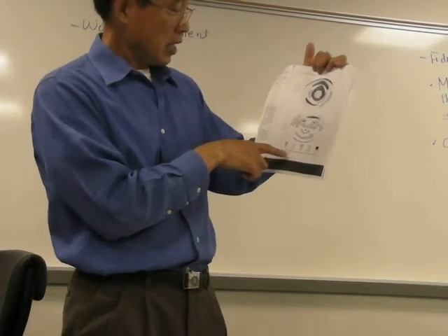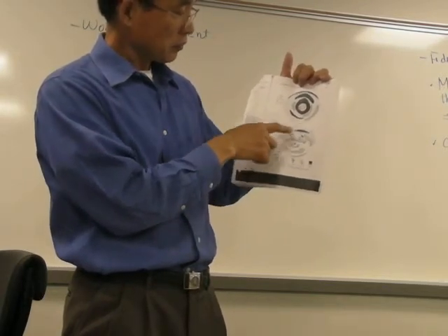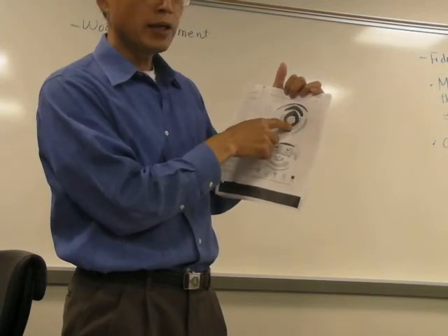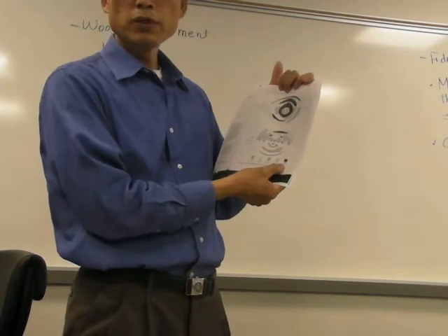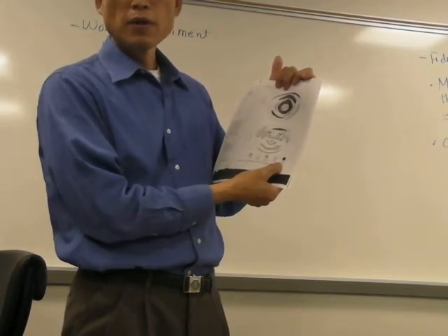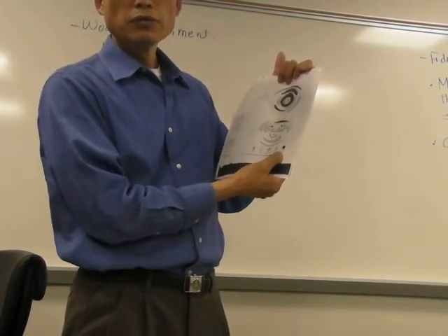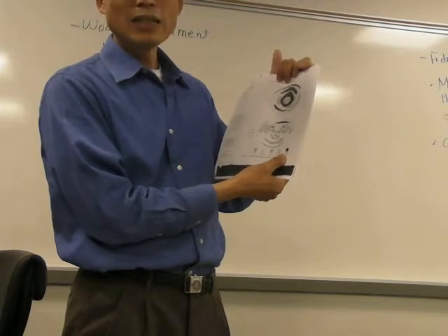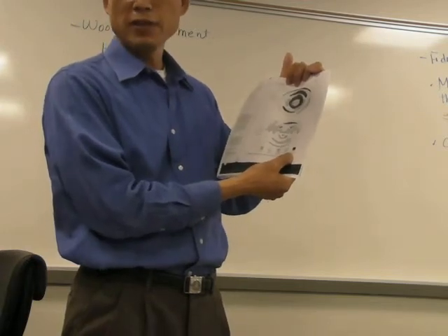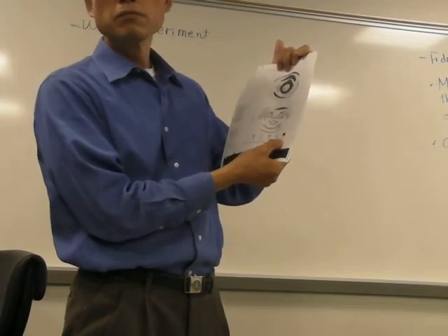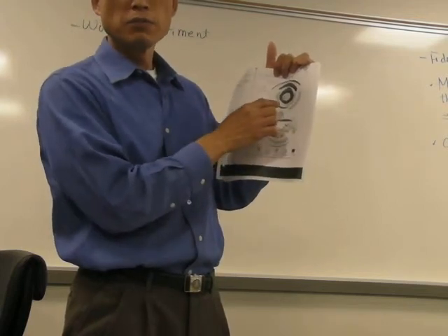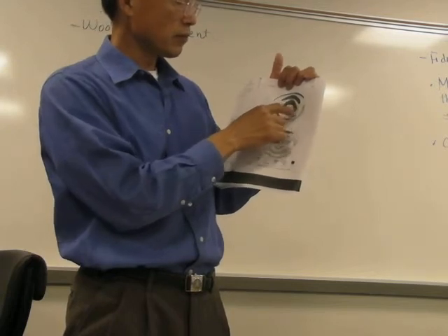You can see ARF. Those black areas are the regions that have ARF lower than 0.125. That means the vibration amplitude was cut down significantly, right? Only 12.5% of the vibration was transmitted in those areas.